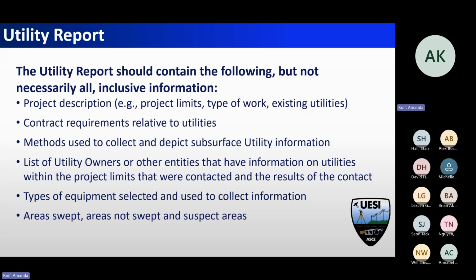Something else, again, is just the type of equipment. So that selection, they're using GPR. There's single channel GPR, there's multi-channel GPR, there's single channel multi-frequency GPR. So there's a lot of different versions of that as well. Just because you're going to use GPR, you need to know which one you're using and what kind of frequency, because you could get different data depending on the type that you're using. So again, just understanding what's required.